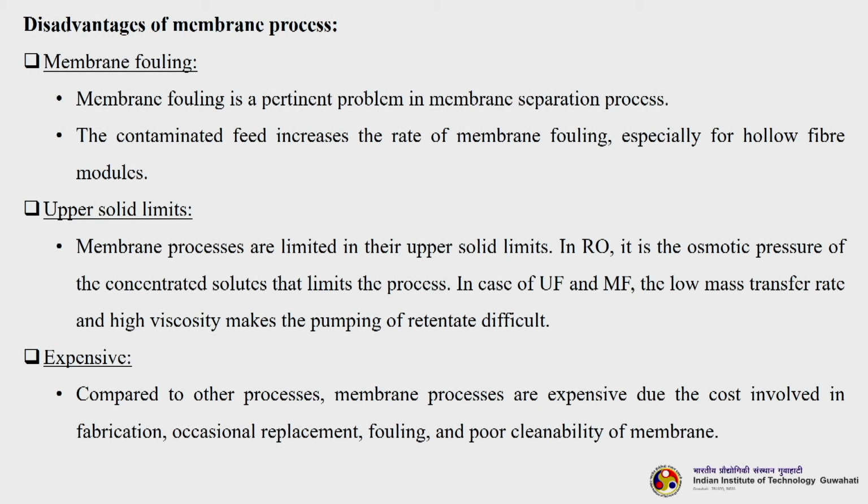So, what is the meaning of this? Now, in RO, reverse osmosis, it is the osmotic pressure of the concentrated solutes that limits the process. Okay. So, in RO you have to just cross the barrier of the osmotic pressure, then only by providing a mechanical pressure in excess of the osmotic pressure, the separation will happen.